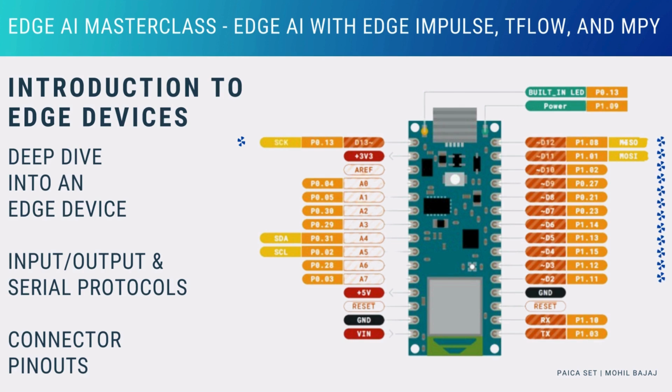Now that we know how a PWM pin works and how to identify it on the pinout diagram, let's understand why we need it in the first place. Why not connect the external device directly to an analog pin? The reason is that many digital systems, like microcontrollers, cannot directly output analog signals. They would need a digital-to-analog converter, or DAC, which would increase cost and the size of an edge device, both of which are highly undesirable.